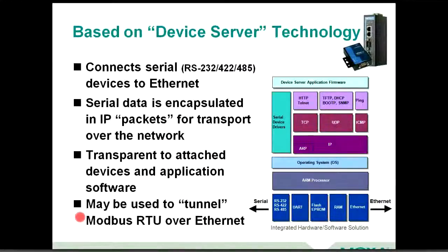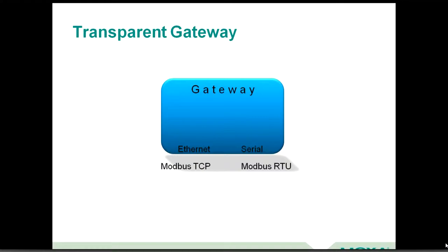There are some caveats with that. You can only do point-to-point connections. You're limited to one device and one master. There are also some caveats in terms of timing. You have to be a little careful setting this up because of the way Modbus works for an end of message, which is typically 3.5 character times. So if we're talking about 9,600 bits per second, that's about a millisecond per character. So at the end of that message, about 4 milliseconds, you've got to be able to stop that communication and let the master take over. So again, if you need help on that, let us know. We can show you how to do that. It's certainly a challenge for a lot of folks and not what everybody needs when they talk about Modbus TCP.